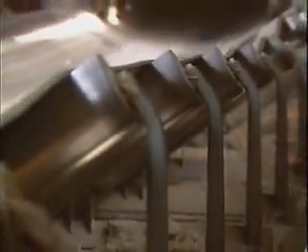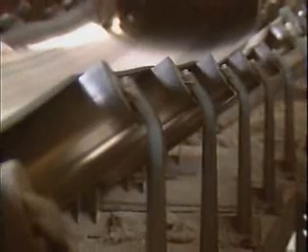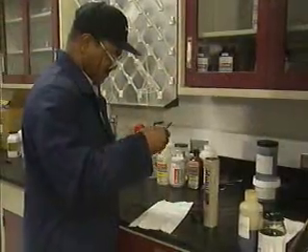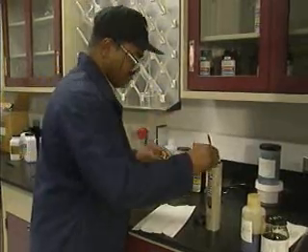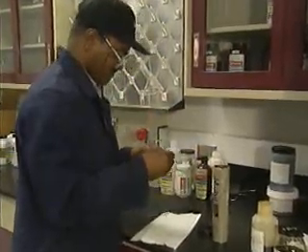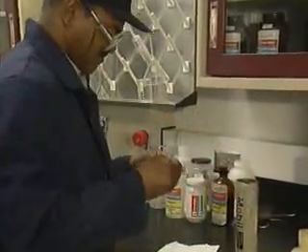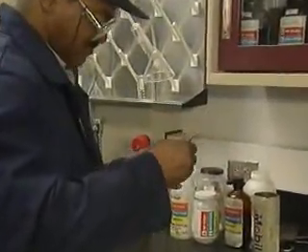If the operating temperature in an area is higher than a grease's drop point, the grease tends to flow away from the area that needs lubrication. So a grease's drop point is normally considered the highest temperature at which the grease can be used. Some greases don't have a drop point. Instead, when heat is applied, the grease begins to decompose chemically before it reaches the point where the thickener in the grease would break down and drops would form.